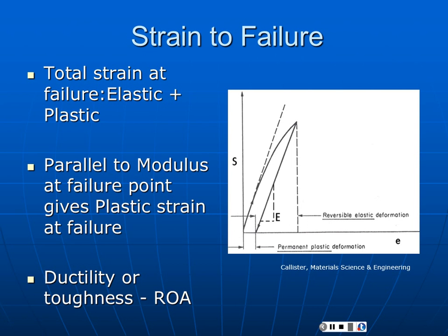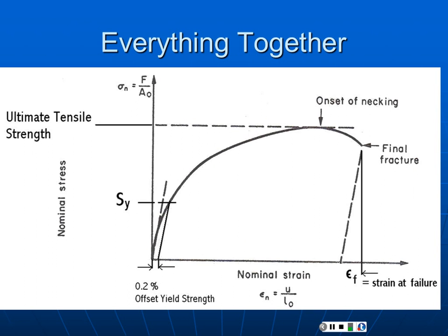Okay, so this is an estimate of ductility, and it's comparable to the reduction of area. So they're both telling us similar things. In fact, this should be proportional. The plastic component particularly should be proportional to the reduction of area, which is a measure of plastic strain in the lateral direction. So that's everything that you can pull out together on a stress strain curve, and we're going to have a separate video where we'll walk through calculations of all of these things with you, as well as obviously we're going to be doing this in class.